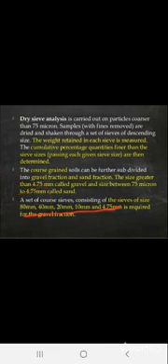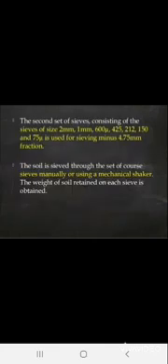Okay, now going ahead, the second set of sieves consists of sieve sizes that are lower, starting from 2 mm, 1 mm, 600 micron, 425, 212, 150 and 75 micron, used to sieve the minus 4.75 mm fraction. So whatever fraction we have collected from the last sieve, we then have to sieve through that number of sieves further.